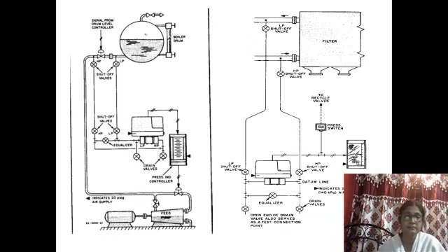This is the real process manual from a certain plant. This is the valve and the boiler drum. This is the three valve type manifold. The equalizer is there, and the high pressure side, this is the DP cell. The high pressure side and low pressure side are connected. Exactly a similar type of operation. This is the detailed plant diagram.